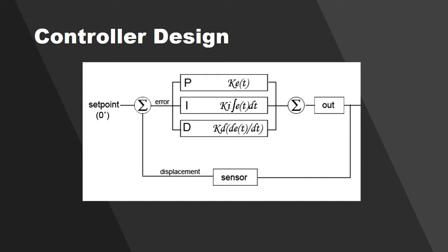The goal of a PID loop is to use data from the feedback device to adjust the output until it has reached the target value. So a settling time for a PID design would be 0.04 seconds, an overshoot of less than 16%, and no steady state error even in the presence of a step disturbance input.